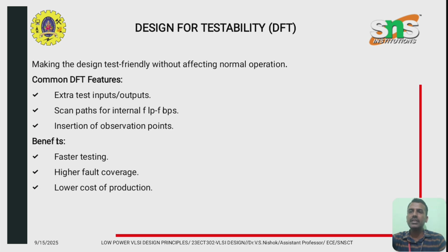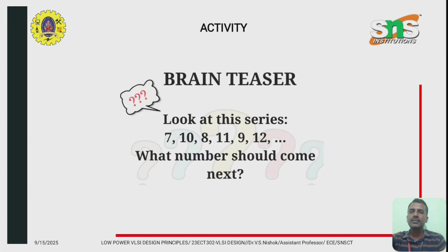Scan path for internal flip-flops: we connect the shift registers additionally and check whether the sequential circuits are functioning perfectly. The main advantages of using DFT are faster testing, higher fault coverage, and lower cost of production. So this is the time for the activity.